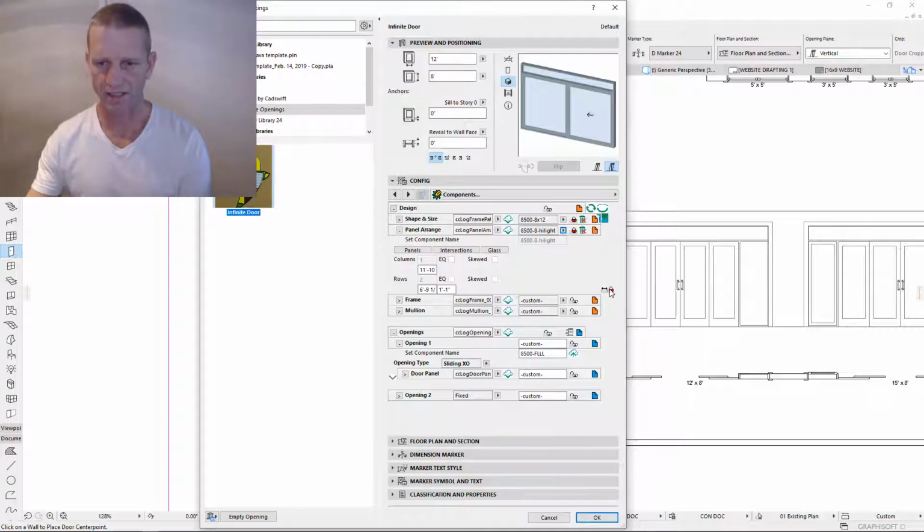So I should have mentioned that there's an apply sizes. So you can lock the arrangement of 1 column by 2 rows, or you can also lock it with its sizes. So if we have a look now, if I try and change this to 5, you can see it won't let me change it. However, if I had turned this off, unlock that, turn that off, and update this, then these sizes will still be editable, but the columns and rows will not. Okay, let's just lock that element down.